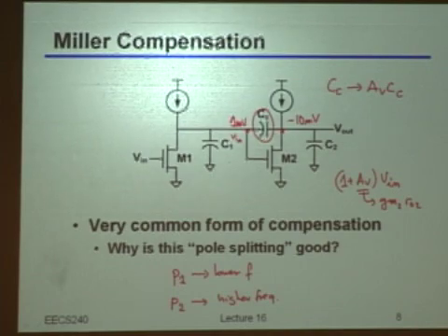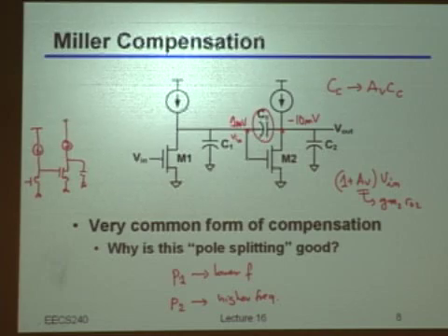So what's happening at high frequency? At high frequency, I can assume that the first pole has already basically done its job. So what can I assume on this circuit? That CC is kind of grounded or shorted, the terminal of CC. So actually my amplifier now looks like that: the first stage, and then the second stage with some cap, and diode connection.